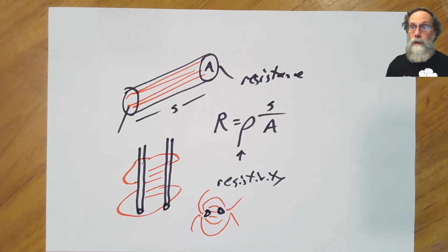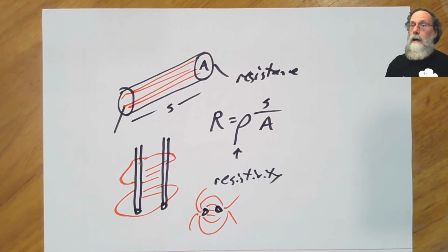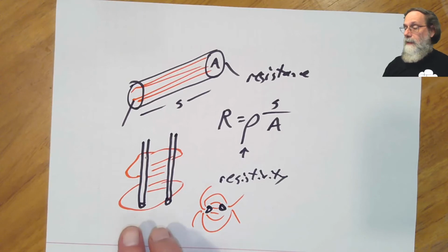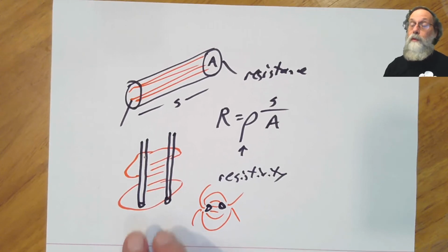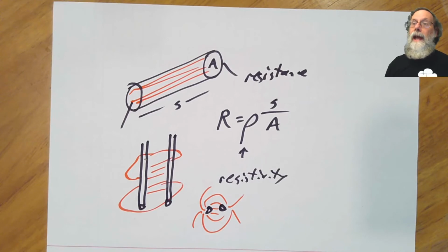And so what people usually do is, when they want to measure something, they take their electrode configuration, whatever it is in the real world, and use a known resistivity solution, a particular concentration at a particular temperature, so they know exactly what it is theoretically, use that as a standard, measure its resistance, and then they can measure resistance of an unknown and have a calibrated geometric factor based on actual measurements of a known solution.